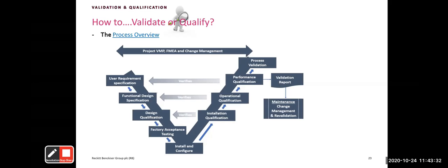And these you capture in your protocols. So all these elements, the electrical requirements, the mechanical requirements, you ask for things that would confirm what you requested from your user requirements specification. And you have the engineer confirming that these things will deliver as expected in your protocol. So you have spaces for each of them, and then you challenge them. Once this is done, you move on to the operational qualification.